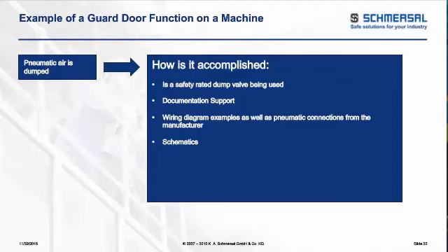The pneumatic dump. In a case like this, we may have seen in the machine that the safe condition is to remove the main air pressure coming into the machine. So maybe the machine's being fed with 80 psi. A lot of people tend to stop at the wire, stop at the motor, and put a single standard dump valve on the machine, as they've always done.